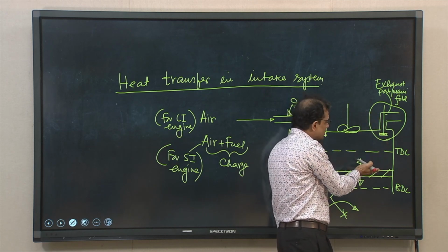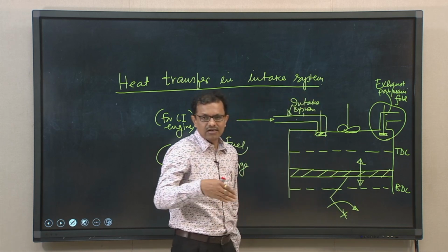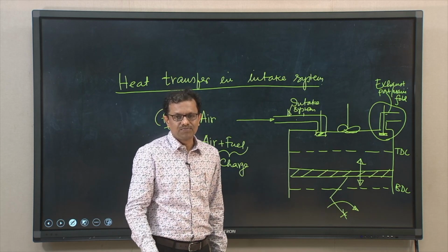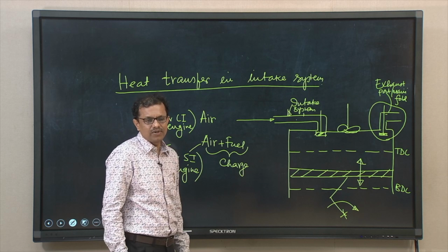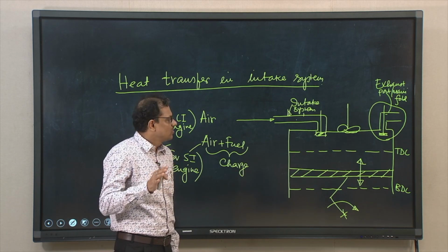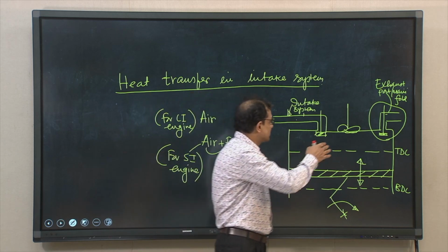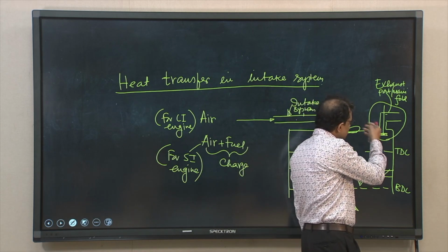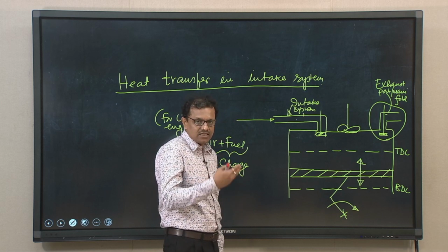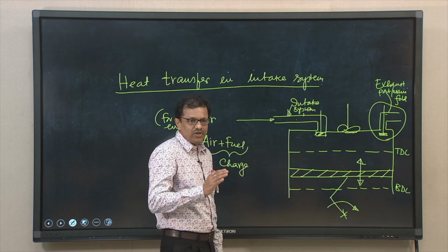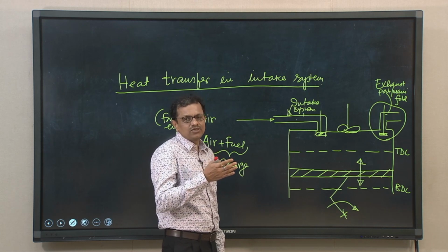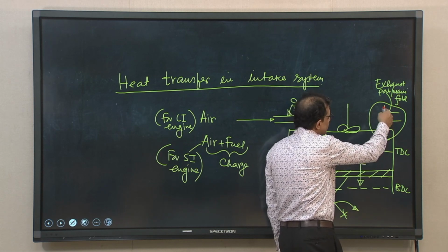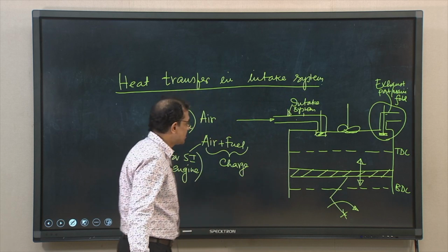In the next stroke, when combustion gases leave through this path, those hot gases again will try to increase the temperature of that system. So, that part is very critical, but again I am repeating, we really do not have the provision of having a cooling system therein. So, lack of integration of a cooling system in this area makes the scenario even more difficult, and that way we have to have some arrangement so as to remove a certain amount of heat from that part, and the melting or possible mechanical failure of this part can be prevented or attenuated.